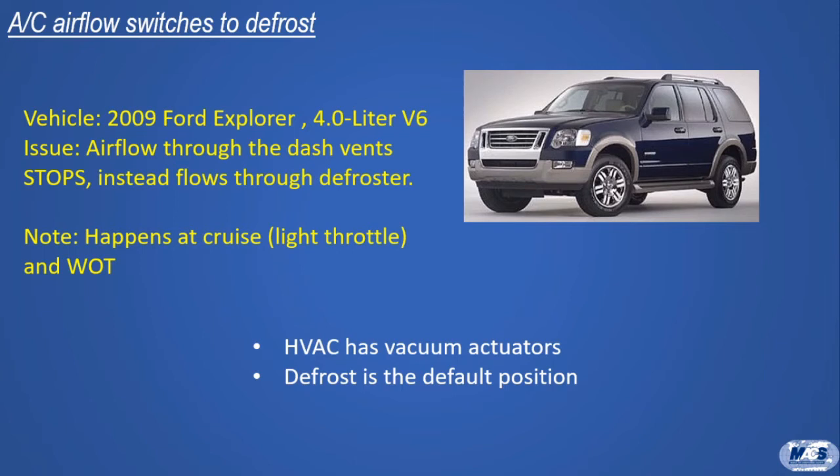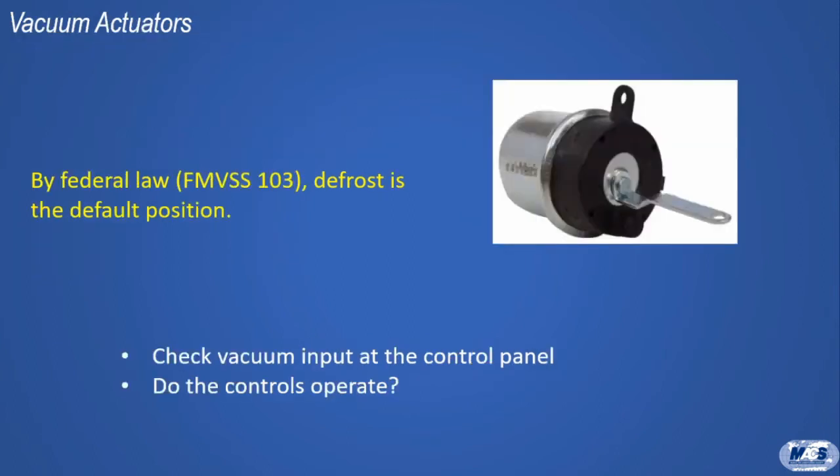A brief time later, the flow would resume from the registers when the driver took his foot off the gas pedal. The symptom also occurred during hard acceleration, or wide open throttle. The HVAC has vacuum actuators, and defrost is the default position when vacuum is lost. Probably a cracked vacuum hose or neck on the reservoir.